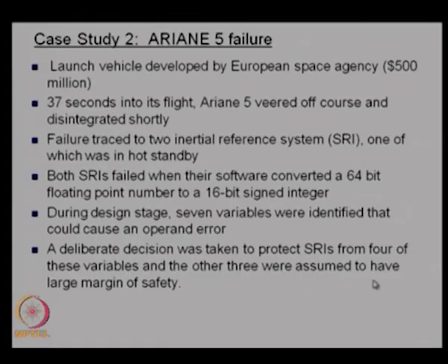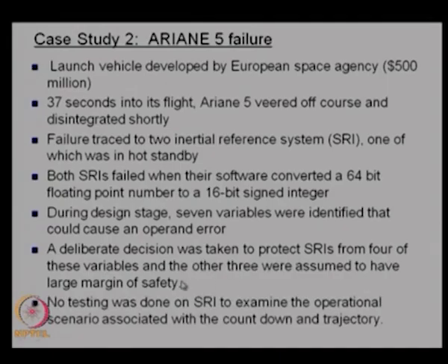and the other 3 were assumed to have a large margin of safety. So again they took a decision here saying that the possibility of these 3 resulting into an operand error is very remote, and then they decided not to protect them against these 3 variables. And no testing was done on SRI to examine the operational scenario associated with the countdown and trajectory.